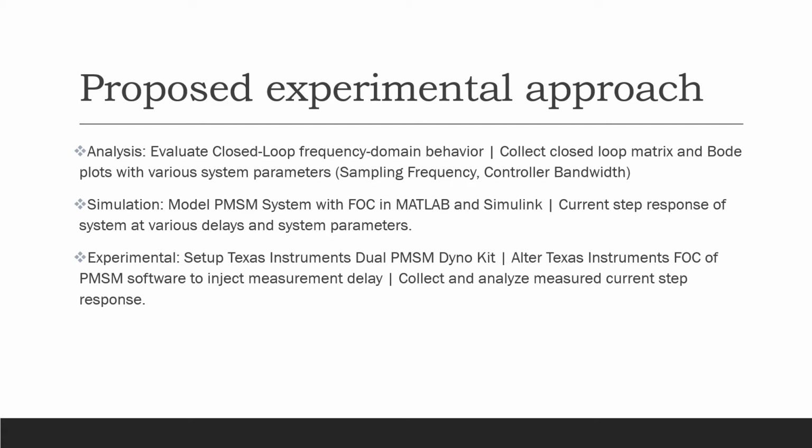And then for simulation, we've modeled the PMSM in Simulink. Using this, we can simulate the system, and we can retrieve the step response of the Q-axis current while injecting varying levels of delays in the feedback current and the position reading. For our experimental setup, we've set up 2 Texas Instruments PMSM controller kits with a dual PMSM dyno. Essentially, this means there are 2 motors whose rotors are hooked onto each other. One motor controls the speed, and the other motor controls the torque of the system.